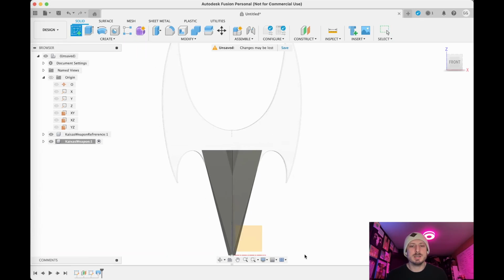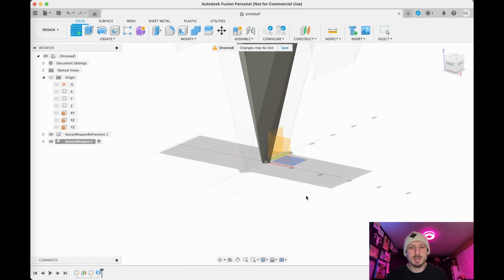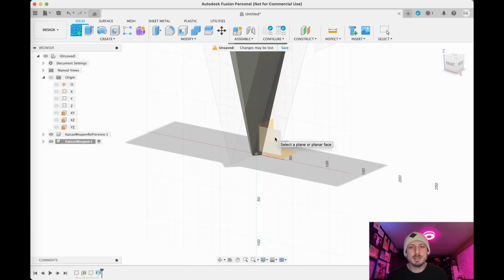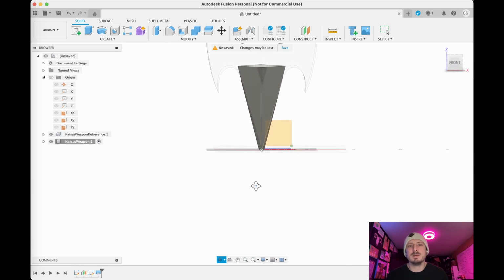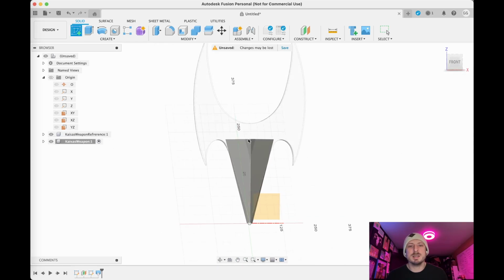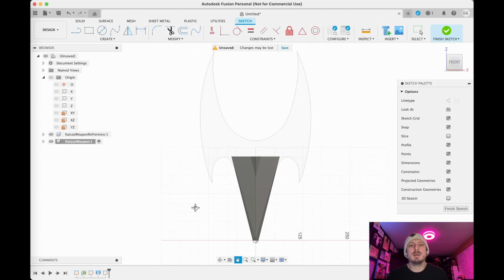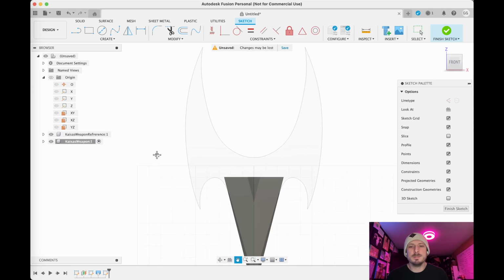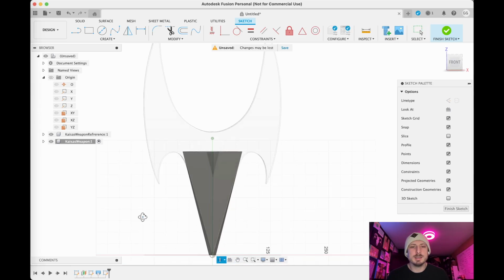So let me hit create sketch and then click on the XZ plane because I want to make right now these profiles that kind of line the direction that we're going to be sweeping. So I'll click the XZ plane and always going to be working on a single side and then using the mirror command to mirror it. So we only care about one side.